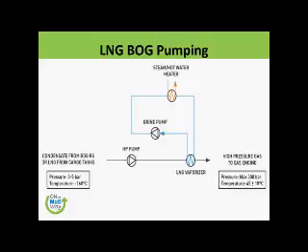They do not have this. So they have the GCUs, gas combustion units, to burn it, where they are just generating the heat, which they will use for different things on board the ships. And sometimes if the boil off is too much, they will just do steam dumping.